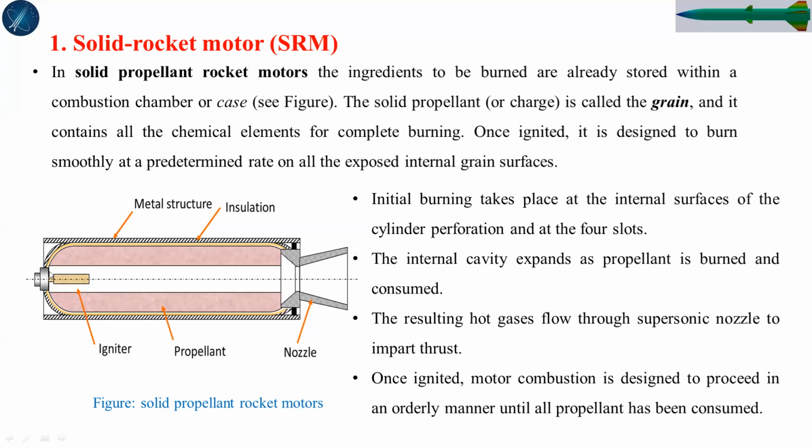Then we have to consider the heat shielding material, that means the insulation material. And then the motor casing or cylindrical casing will come out. That cylindrical casing is designed based on the aerodynamic principle with no external extrusion or extra parts. So it should be a smooth cylinder with appropriate strength in order to overcome the aerodynamic loads and other loads. Okay, so this is what you are expected to design in this course.